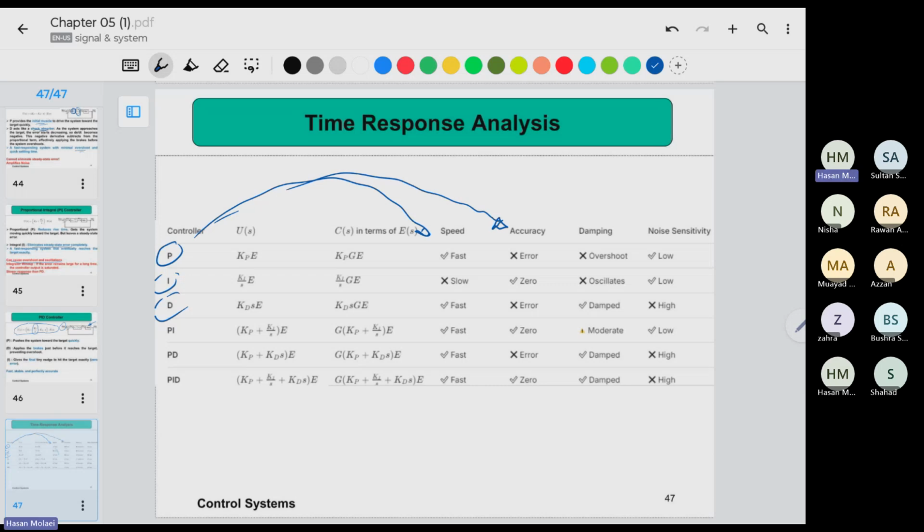The error still may remain. We know that the integrator actually improves the error to 0. Every 1/s improves the final steady state error for higher order signals, but it might increase the oscillation risk, right?